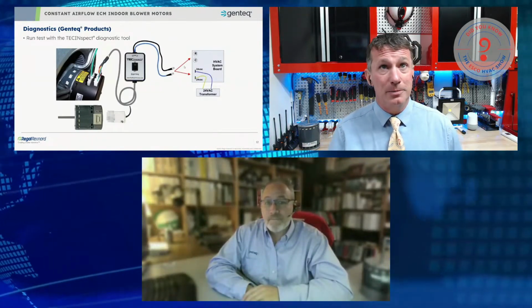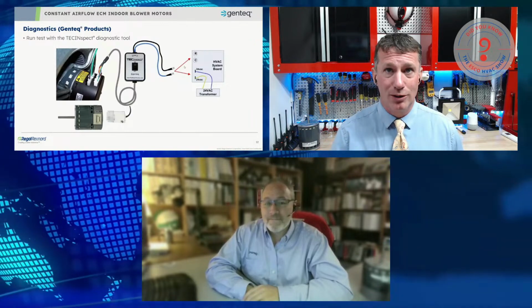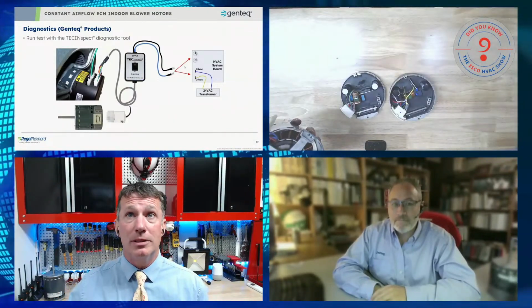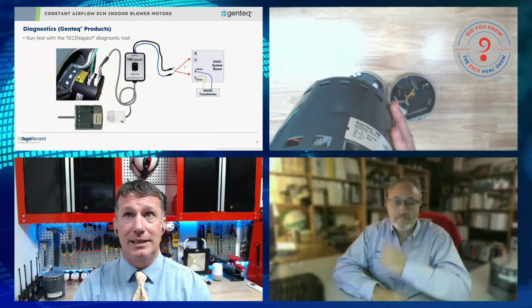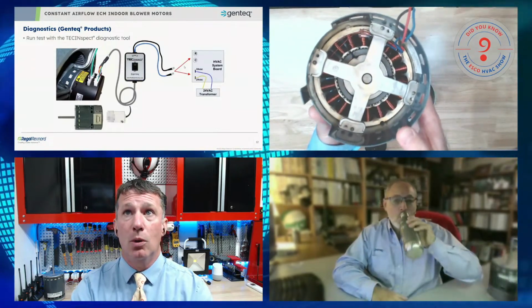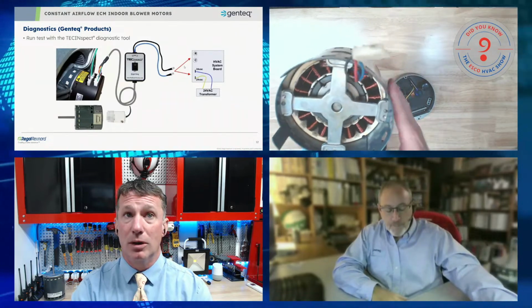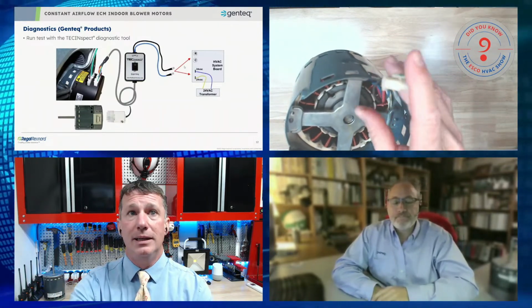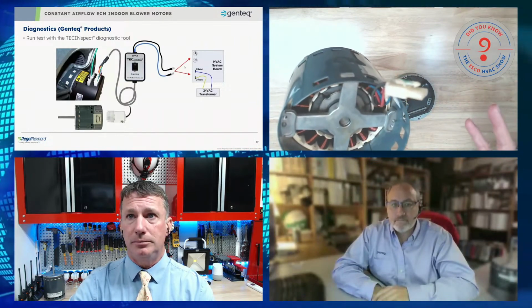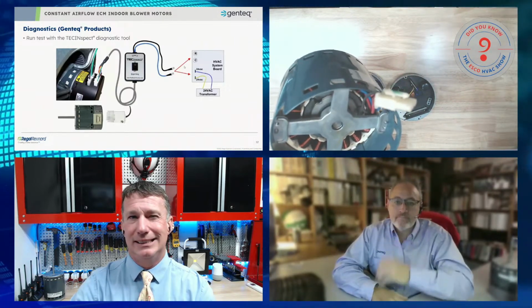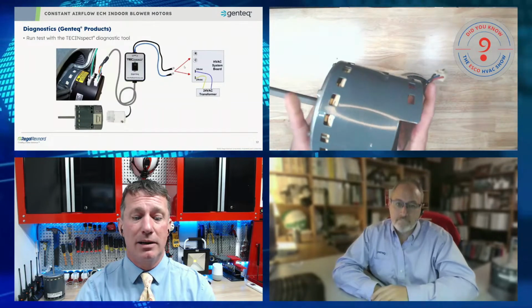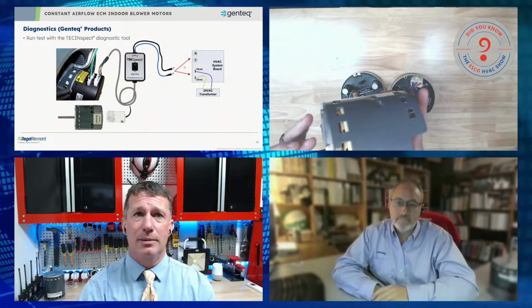You know, a lot of people don't understand how robust the actual motor itself is. I mean, we're talking about a 3-phase motor, right? We're not talking about a permanent split motor that has different resistance windings where one is almost always going to burn out before the other one. We're talking about a very, very robust motor. Honestly, I've only had one in the field that the motor windings themselves were bad. And it was only because I had one winding that was more than a 10% tolerance from the others. It was like 25, 30%. I thought, well, that's out there. But the actual motor itself had not burnt out, right? They're very robust. They got good bearings to them. And so we don't do a lot of damage to the motor itself.